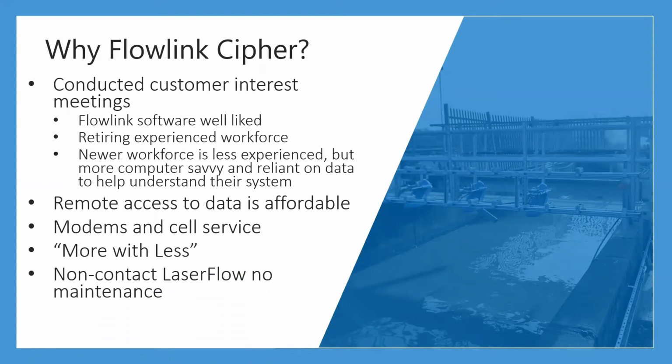And then when you have something like the LaserFlow, which is a non-contact area velocity meter, now you have a no maintenance device. Why do I need to go out and download if I can have something that's going to give me good, accurate, reliable data without going to the field? And then finally, no IT involvement. A lot of us have experienced this over the years. You make changes to software, your IT group has to get involved to update the software, firmware, and things like that. Not a good time for anybody. So we wanted to minimize or eliminate as much as possible the IT involvement.